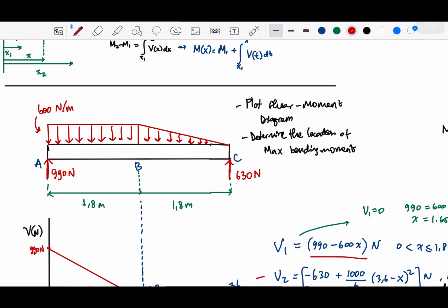So you can see that from here up to here, you will see some change in shear, right? You can predict how it looks, and then to get the moment, take the integrations from that graph. But for the exact value, we need to go back to our equations.